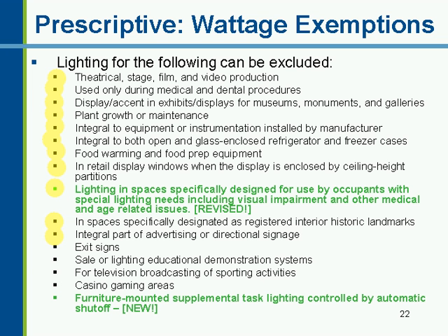If you have lights that are part of a sign, again, it's part of the equipment that comes from the manufacturer, that's exempted. Exit signs are exempted. Now, you'll recall there was an exit sign requirement. The exit signs do not have to be counted in the wattage calculation, but the other requirement that they must be 5 watts per face is still in place, so both requirements apply. Sale for lighting or educational demonstration systems does not have to be counted. For television broadcasting and sporting activities, again, similar to theatrical production, it's just the lighting used for the actual television broadcasting. All the other general lighting has to be counted.